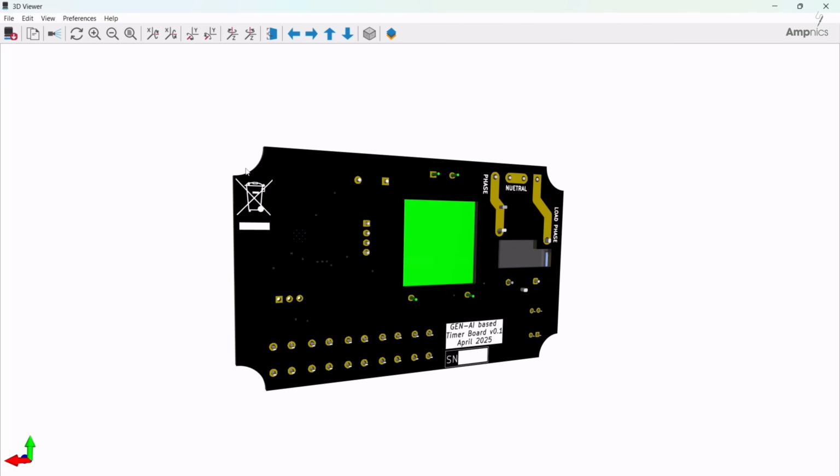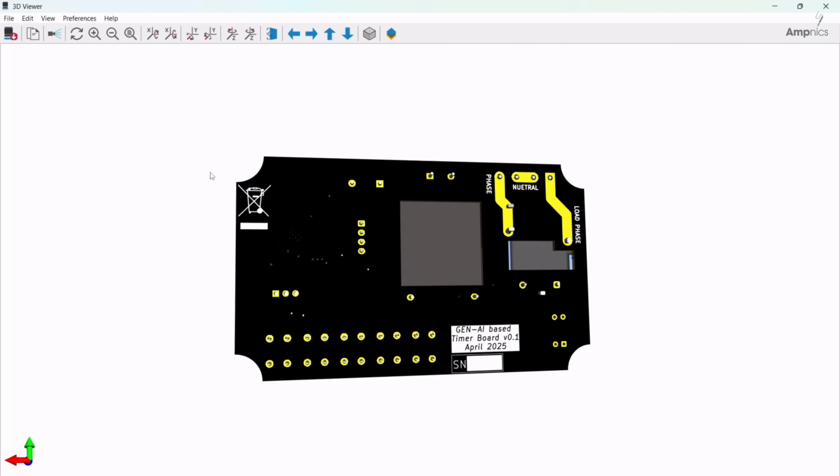Okay, so if you see here, basically what I did, I created a cutout. In the relay section and the high link section, this high link cutout is not necessary, but I did it for my own convenience. If you don't want to do it, you can. And for here it is required, because this relay is switching high voltage and high current devices. You are driving this relay from 5 volt, so you need to make an isolation here. That is what I exactly did here.